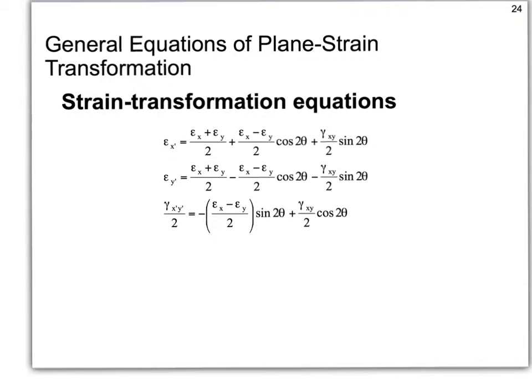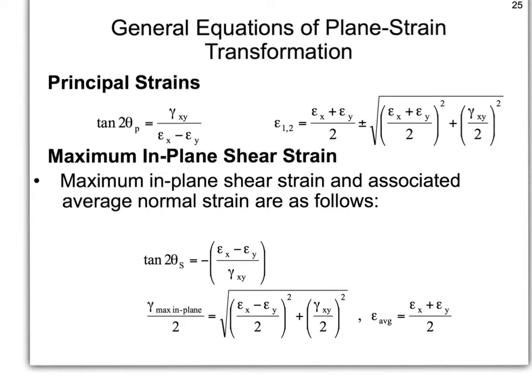From those equations we can find the principal strains and the maximum in-plane shear strain using similar equations to what we saw before with the stress, but with the factor of 2 in there to take into account the difference between the shear strain and the shear stress.